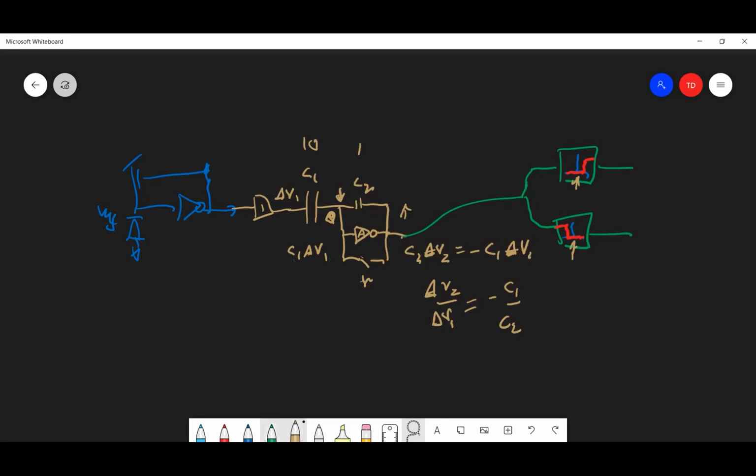So then the result of that will be that if the logarithmic voltage goes up past the threshold, you get an on event. And if it goes down past the negative threshold, you'll get an off event. So that's how the pixel works. Every time there's an event that comes from the pixel, you get either a digital on or a digital off event.